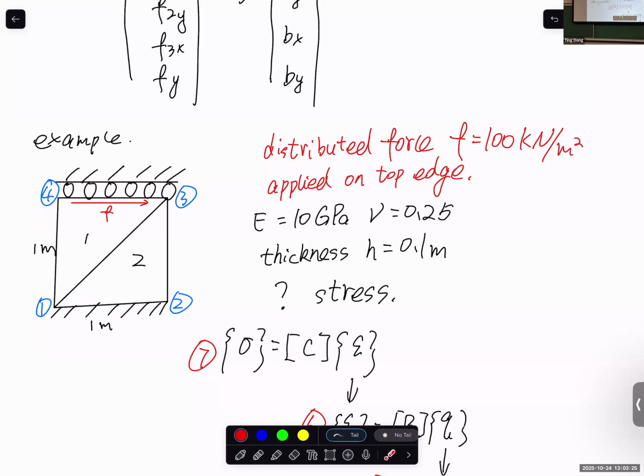And if the bending moment changes in the structure, let's say I apply a contrary force at this point, and the bending moment changes through the whole beam, there is also shear stress caused by bending. But here, we don't have bending moment applied. We don't have tension compression force in the X direction. We don't have tension compression force in the Y direction. So there's no normal strain in X and no normal strain in Y. We only have shear strain. And this shear stress from mechanics of materials should be the force applied on the edge divided by this area. It's constant through the structure. Make sense or not?